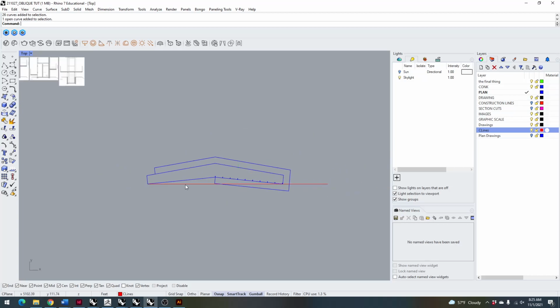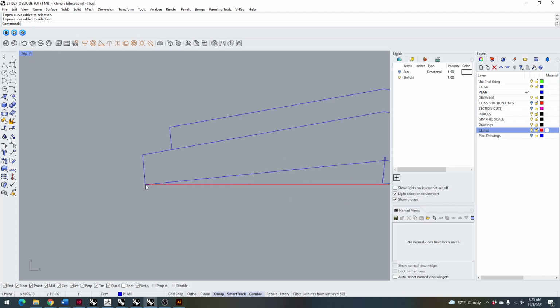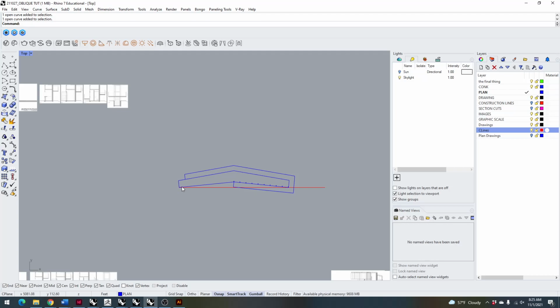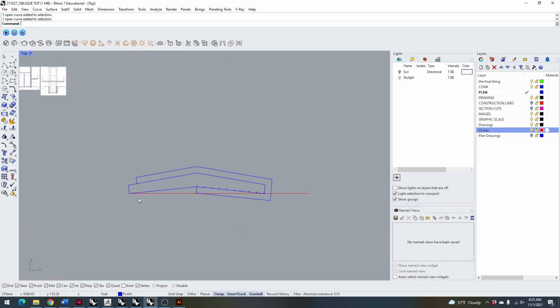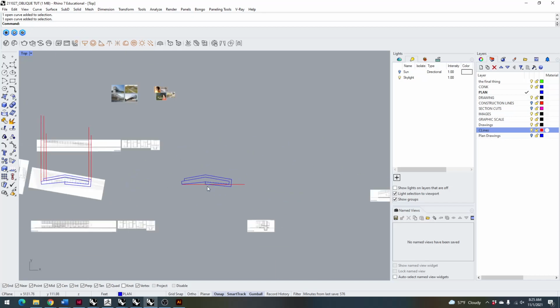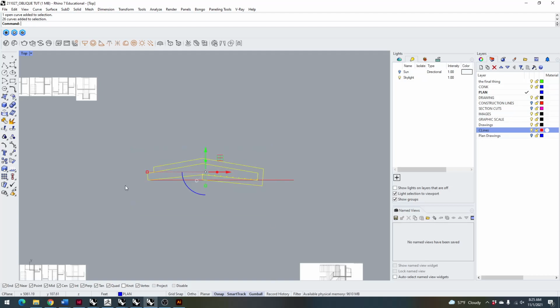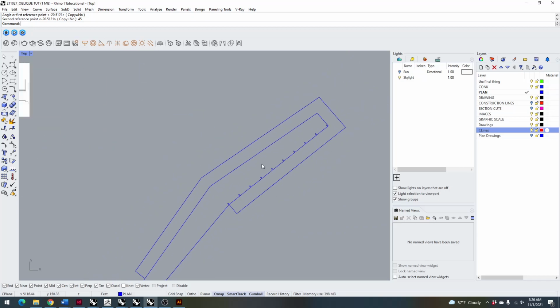So what I've done here is I'm just adding a reference line, a datum, from which I'll rotate this plan. That way I know how to get my plan back to its original orientation, or I'll know how to rotate things, a point to rotate them from, if I need to bring things from my traced plan back over to my plan oblique. So now I'll type the rotate command and rotate over, and then type in 45 degrees. And now I have a 45 degree drawing.